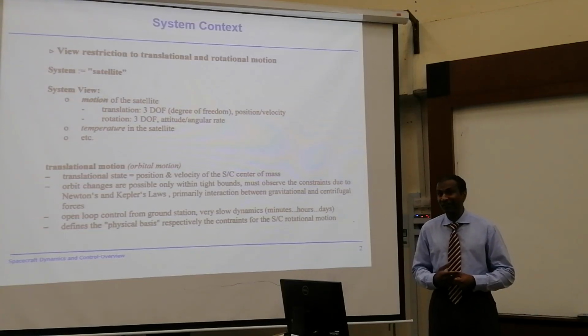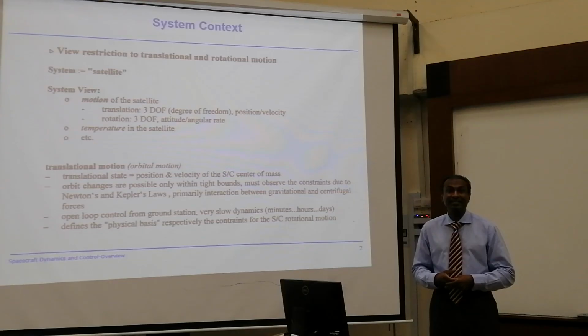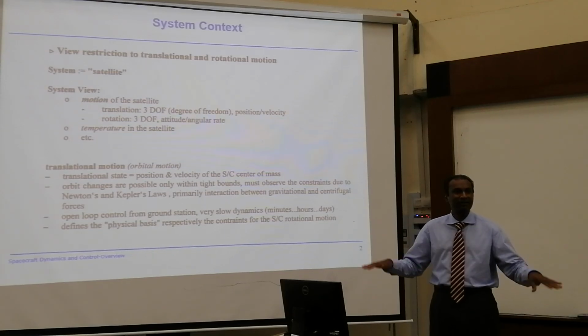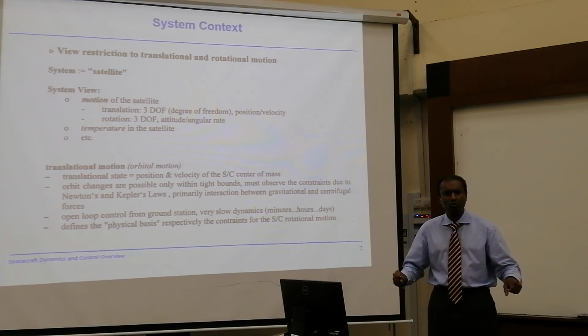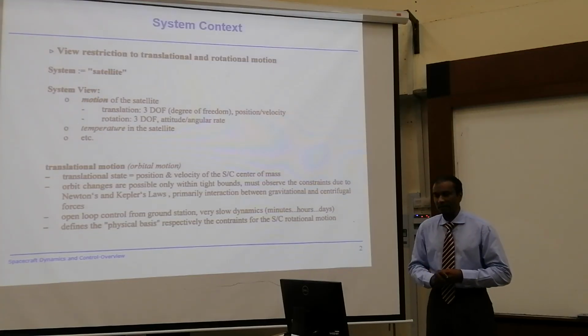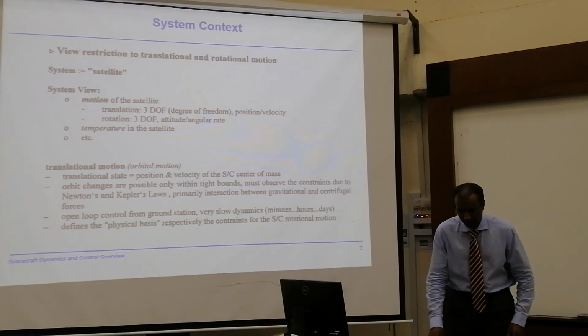And it is going to be very costly because a lot of fuel needs to be used. And we know for a fact that the last thing that we want to do in space mechanics, in orbit correction, is inclination change. Right? Inclination change is very, very costly. That means so much fuel you are going to use. So you don't do it often. Or even altitude change, you don't do often because too much fuel.